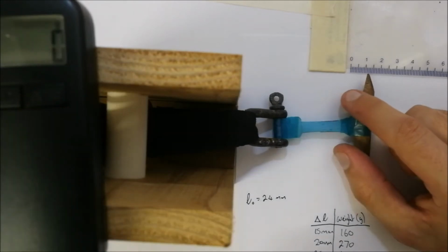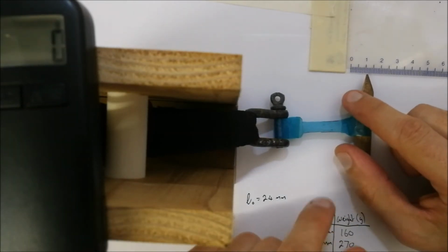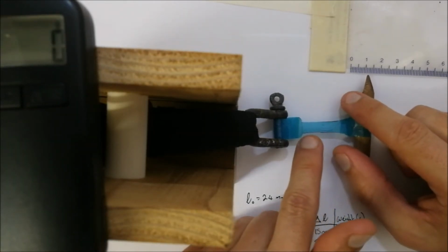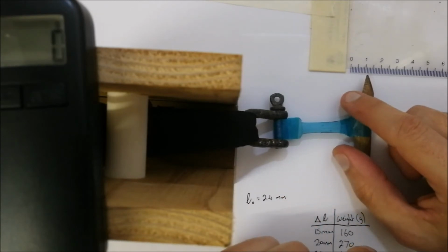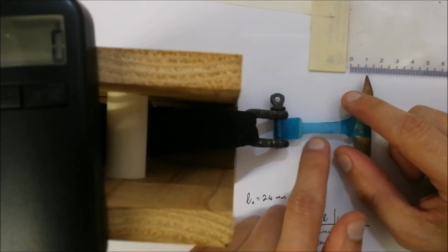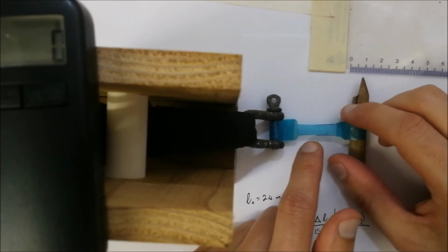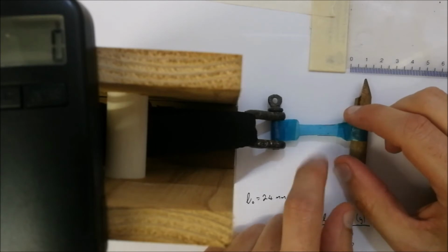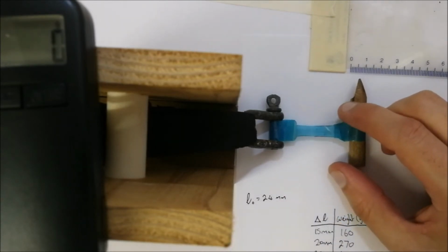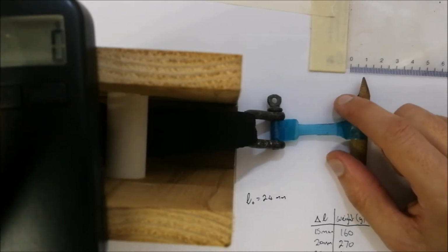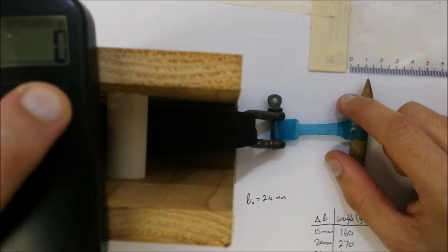Now you'll see over here that already this has stretched quite a substantial amount, because now the 0 position is actually at around 10 millimeters. So that indicates to us it's not at 0 millimeters anymore, as it was originally. This material has stretched a bit, and obviously this necking has become much thinner. Okay, let's move it again and see.